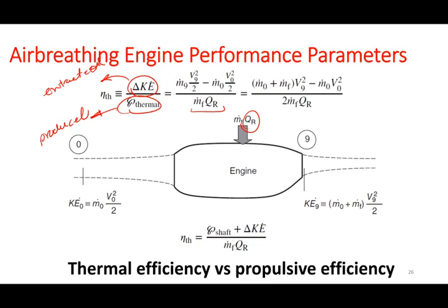Okay, but for some cases, most of the energy is not going to be transformed to kinetic energy. Some of the energy is going to be transformed to shaft energy that is going to rotate the propeller or for other different purposes, right? So sometimes if you have a shaft in your engine that is eating up, for example, 50% of your extracted mechanical energy, you have to include that in your thermal efficiency calculation.